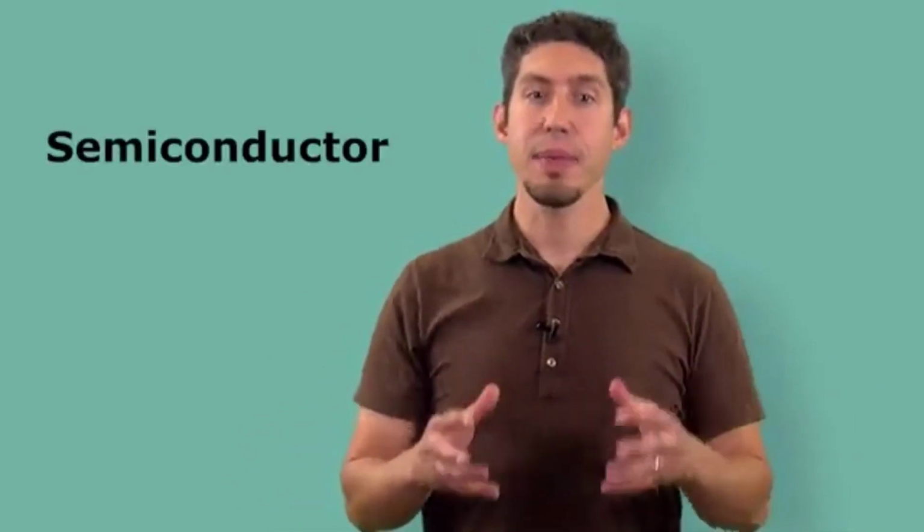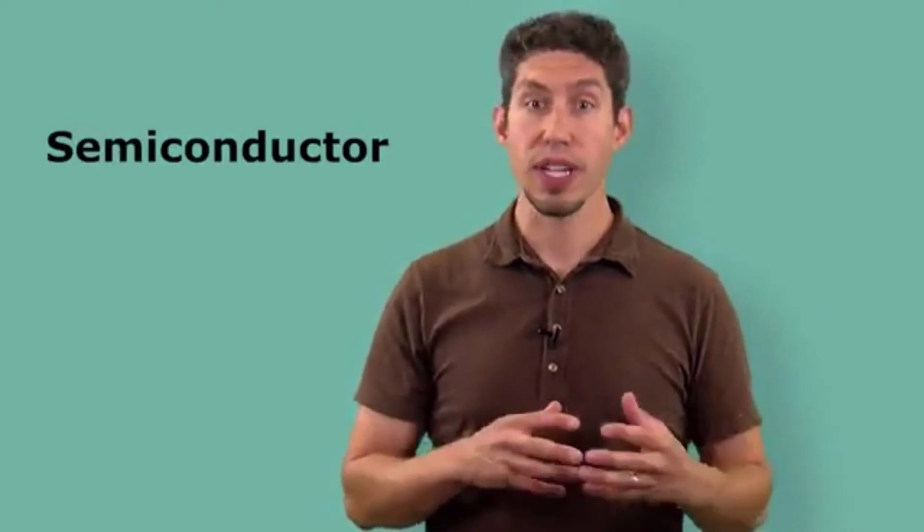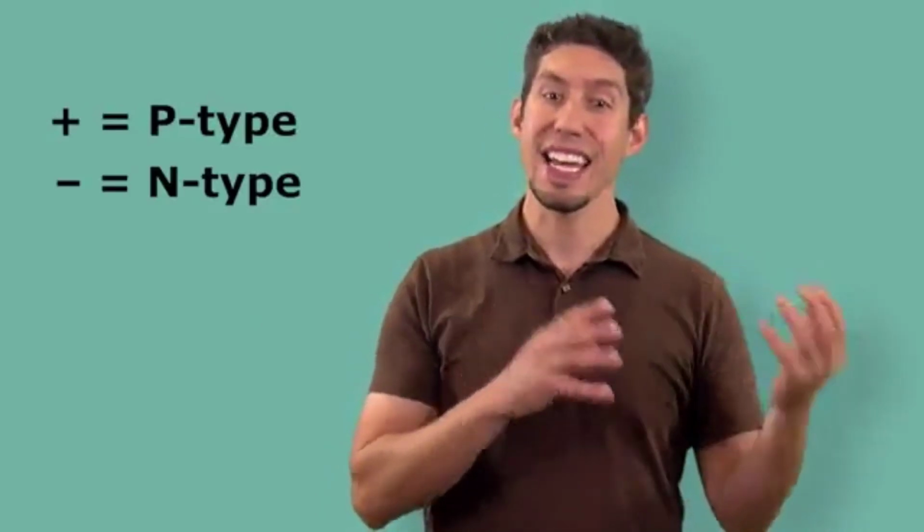So how does the silicon actually convert sunlight into electricity? Well, it's because silicon is a semiconductor, meaning that electrons can flow or conduct under the right conditions. In both monocrystalline and polycrystalline silicon production, there's also a doping process where impurities are specially added to silicon to slightly alter its conductivity and its charge. The typical dopants are boron, which creates a positive charge, or phosphorus, which creates a negative charge. The positive charge is referred to as P-type material, and the negative charge is referred to as N-type material.